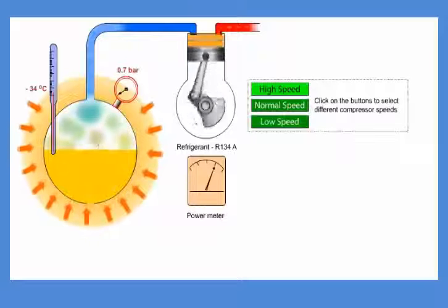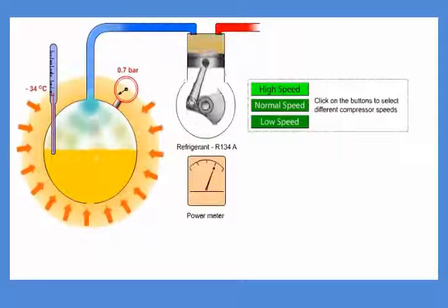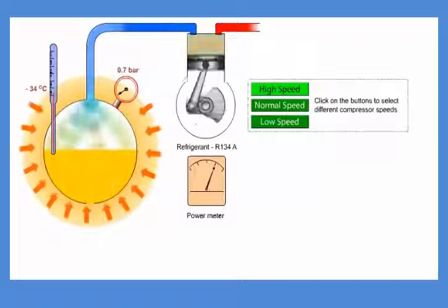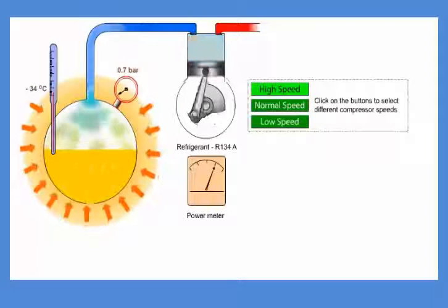The compressor will momentarily try to pump more refrigerant vapor than produced in the flask, with the consequence that the pressure in the flask is pulled down, causing a lower evaporation temperature. This will again cause a more violent evaporation, as you can see, which will continue because the temperature difference between the ambient temperature and the evaporation temperature in the flask is now higher, giving an increase in heat transmission to the flask. A new equilibrium will be established.